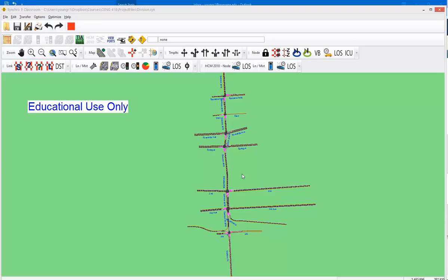So we're going to look first just at some features that weren't that necessary when we had a single intersection, but are pretty helpful when you're looking at an entire corridor. And just to remind you, this is a portion of the Synchro file that the city of Spokane has, and they have a single Synchro file for the entire city. So they look at a lot of their corridors as different zones, and they see about the coordination of entire areas like downtown.